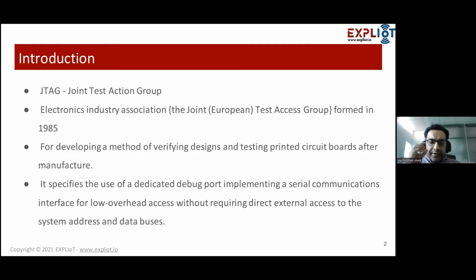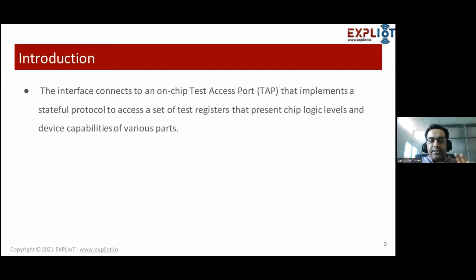The scale of the embedded systems has been reduced to a significant size. Now, to directly access such ports, we have the UART port, we have different ports over there. But when you go specifically to the debug part, we need a kind of stateful protocol, which is what JTAG actually is. The basic thing JTAG is looking for is the test access port, which interacts as a debug port, and eventually it has access to the test registers built into your system, and you can actually play with the chip logic over there. So this is what it is.